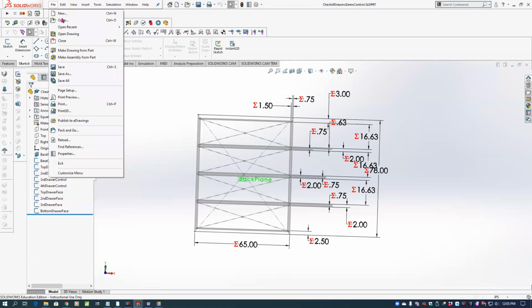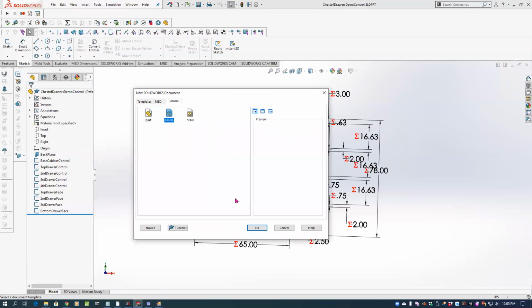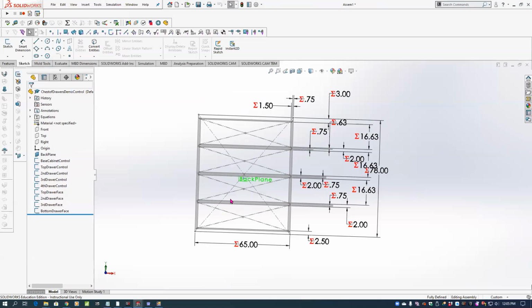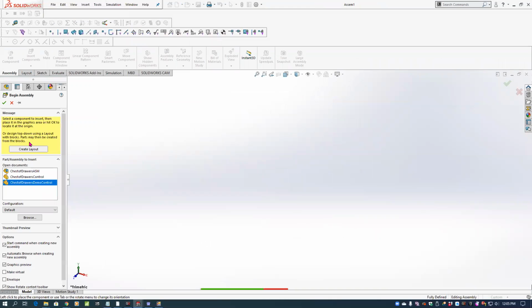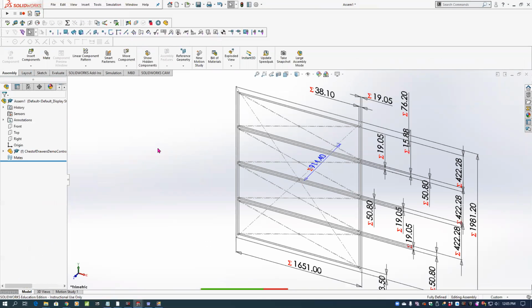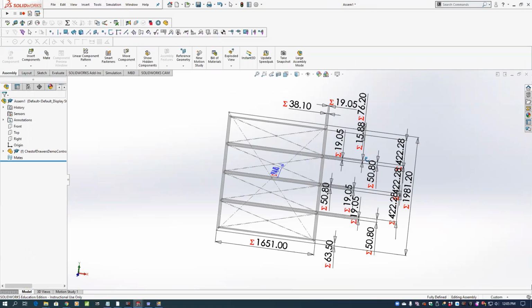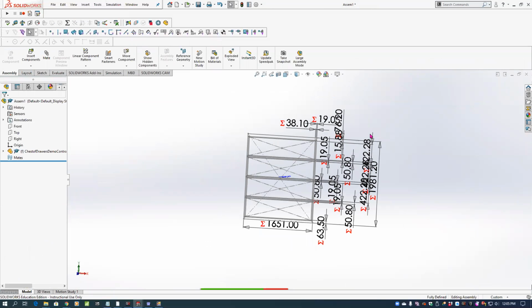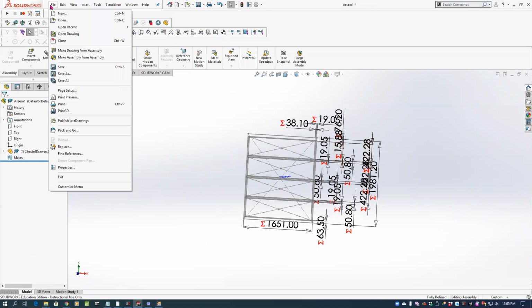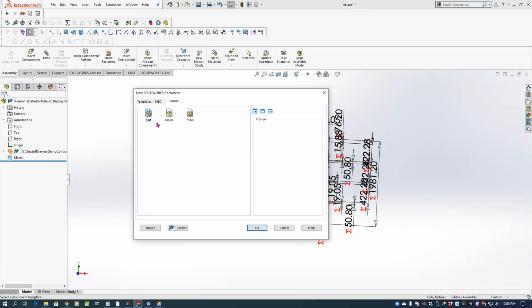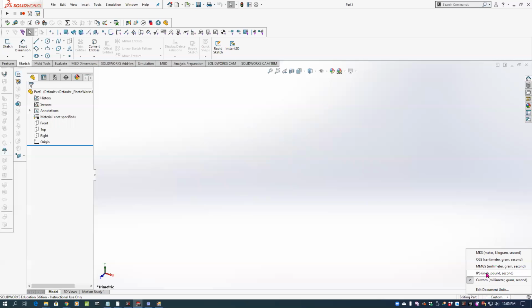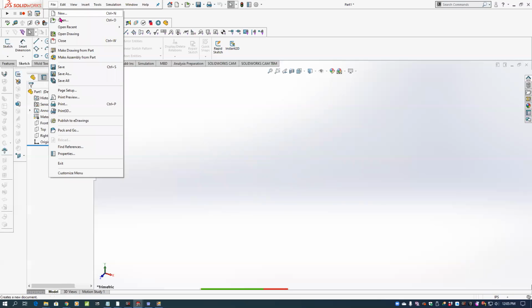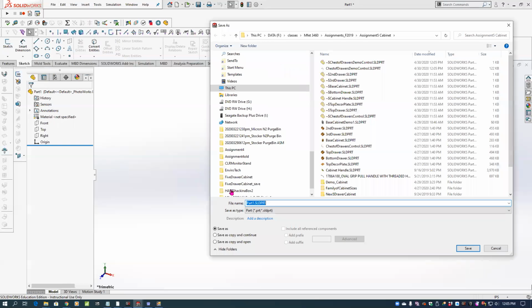And I'll create a new assembly and insert that drawers demo control into the first part in my assembly. And now if I create my chest, my cabinet, and the drawers, I would just say create a new part, and we'll save this off as my cabinet.